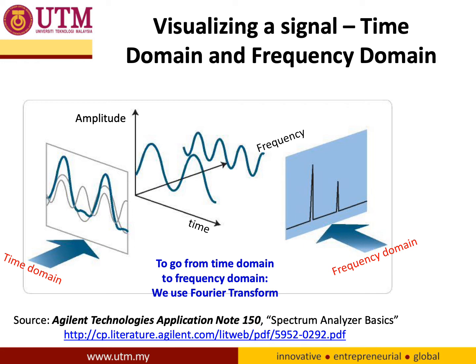A time domain graph can show how a signal changes with time, whereas a frequency domain graph will show how much of the signal lies within each given frequency band over a range of frequency. Frequency domain displays how much of the signal exists within a given frequency band concerning a range of frequency. Also, a frequency domain representation can include information on the phase shift that must be applied to each sinusoid to be able to recombine the frequency components to recover the original signal. This is when we talk about application.